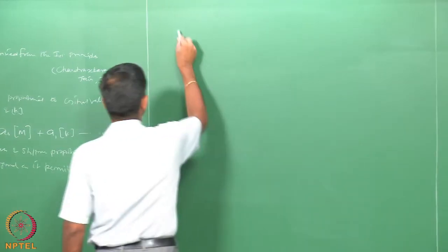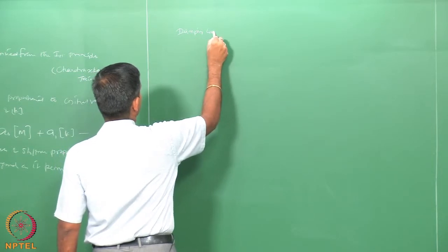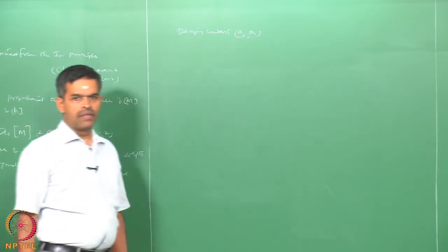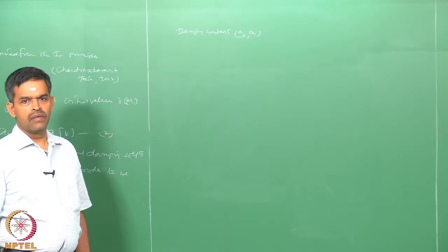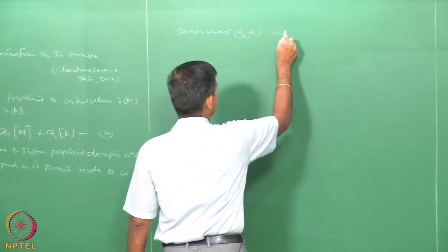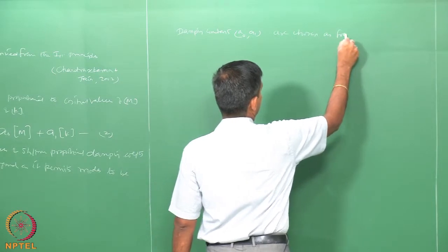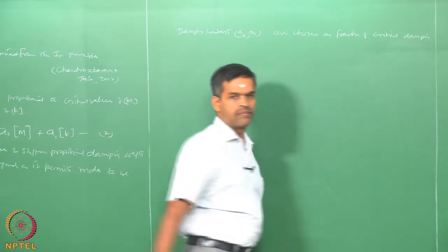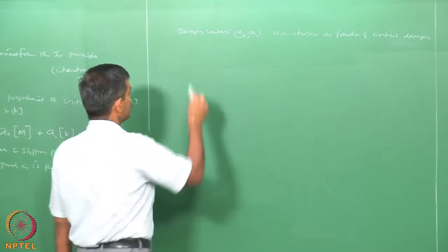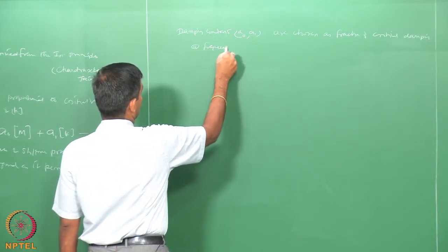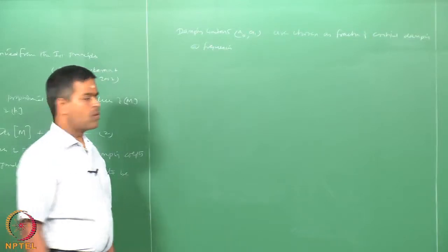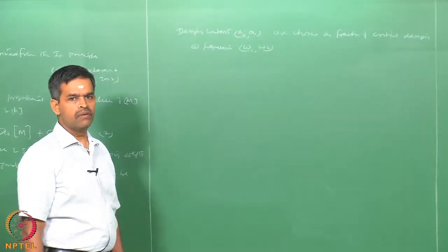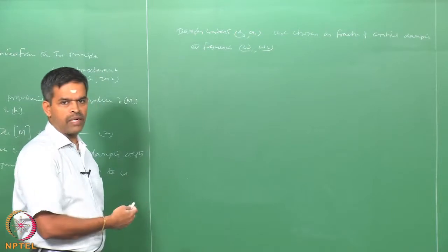The damping constants A0 and A1 interestingly are chosen as fractions of critical damping at frequencies which are omega 1 and omega 2. Okay. So, one can solve the simultaneous equation which I am going to write now.